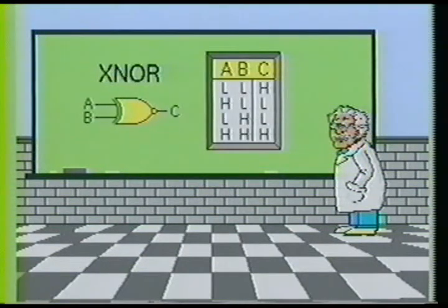The exclusive NOR gate is another commonly found gate circuit used in digital arithmetic circuits. The exclusive NOR gate differs from the exclusive OR gate in that there is an inverter gate placed at its output. This causes the output to go high when both inputs are of the same state of energy. The letters XNOR are often used to designate the exclusive NOR gate circuit.